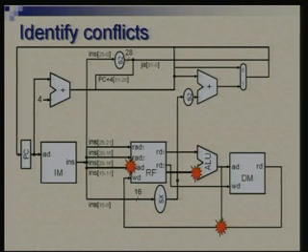and associated with that is this point of conflict, where there are different addresses used to address the write port of the register file. It is either INS 11 to 15 or INS 16 to 20. Different fields in the instruction are addressing the same write port.